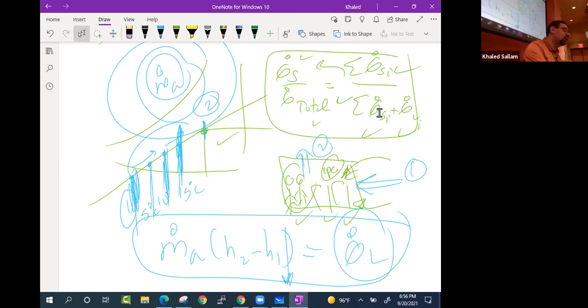So that funny story is really trying to tell you that you don't want a high mass flow rate of air, because that means either really big ducts, which you don't have ceiling for. Maybe here you have ceiling, but in actual offices, you cannot let the ceiling drop too much. So the duct needs to be smaller. You cannot allow them to be big.